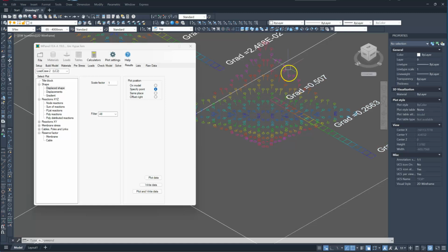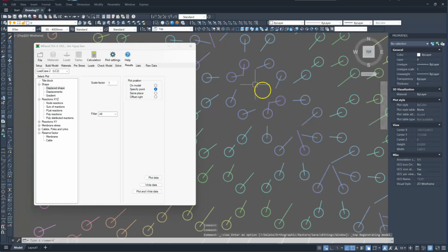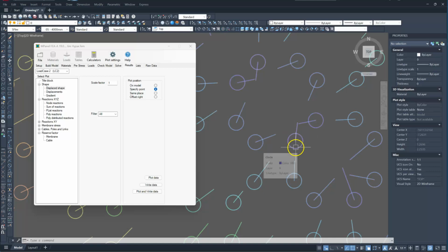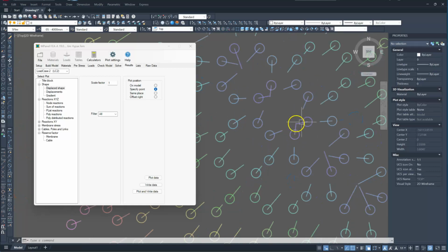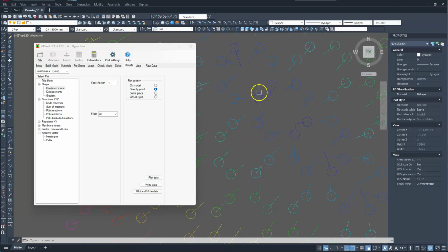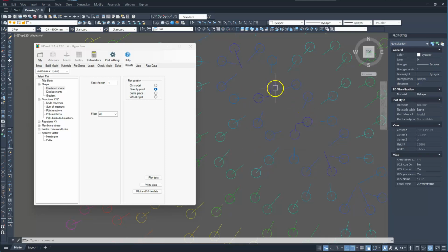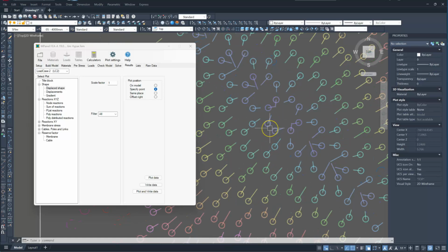And then if we zoom in on the gradient plot, we can see we have these points pointing inwards. So the circle represents a drop of water or rain, and then the direction in which it will flow. And what we're looking for is when these start pointing in towards each other, we know we have a high probability of ponding. So once a small amount of water collects, then we know that this will devolve quite rapidly into most likely a failure.